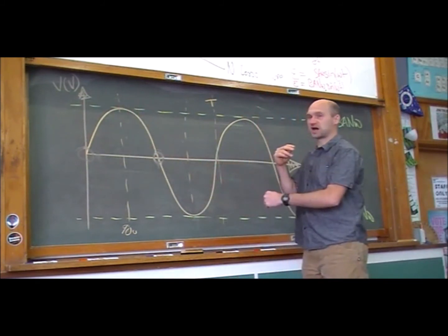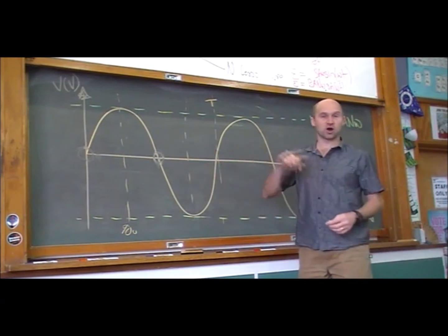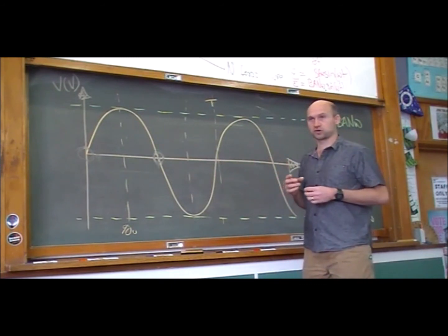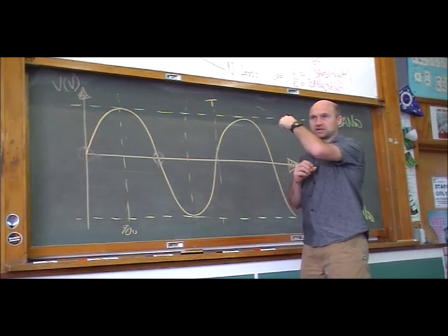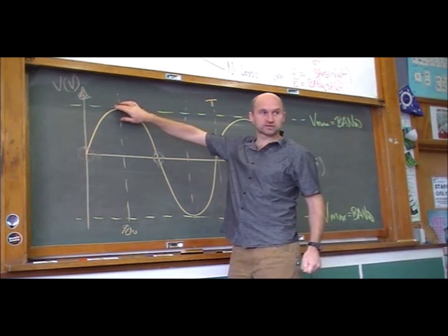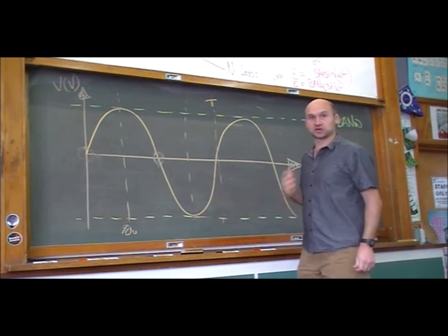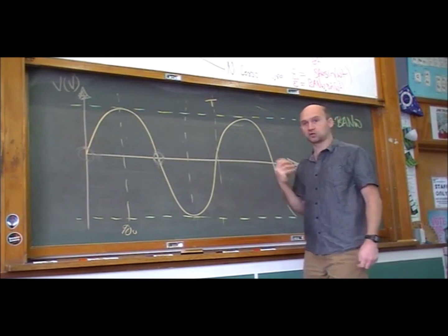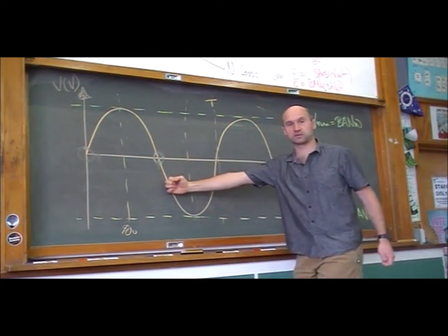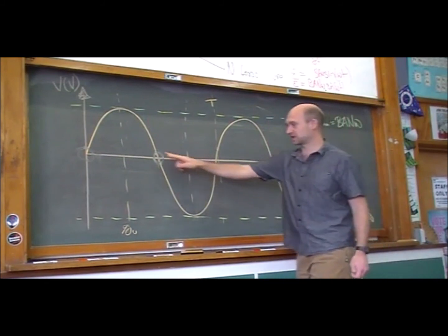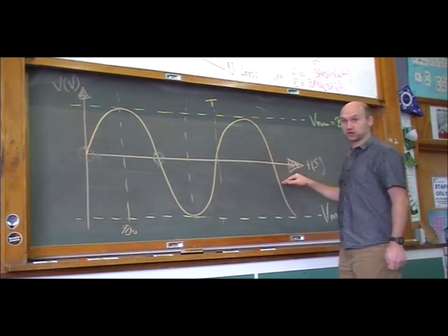The reason that this is a negative and that this is a positive is just that the loop is the other way up, and so that means that the current is now flowing the opposite way through the coil. If the top bit of coil was moved to the bottom, that means that here the current was flowing one way, down here the current's going to be flowing the opposite way, and so lo and behold, we've got that alternating current. First we pushed the current one way, now we've grabbed hold of it and we're pulling it back exactly the same amount the other way, only to push it forward again.